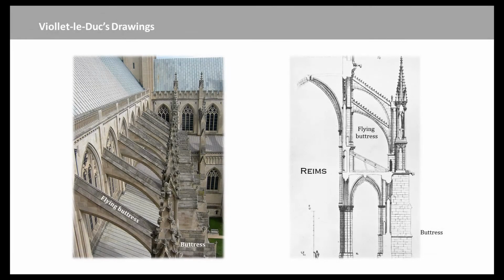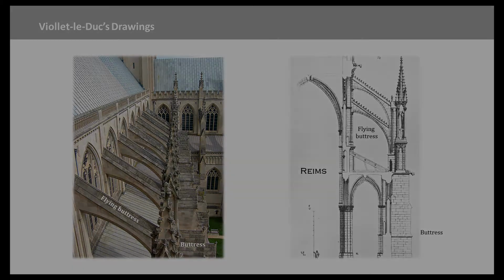The flying buttress is a two-part composite support that features a beam that extends to a massive pier far from the wall, and so provides most of the load-bearing capacity of a traditional buttress, which is engaged with the wall from top to bottom. Thus, the flying buttress is a lighter and more cost-effective architectural structure. In this video, we will study the behavior of the lateral support system.